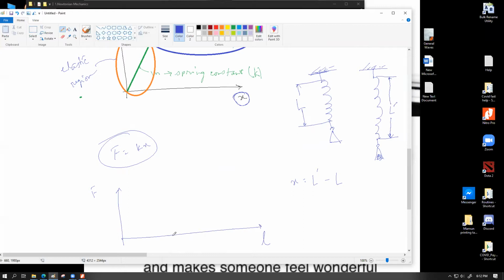So let's say the graph would start from this x-axis intercept, where this value is essentially capital L, the original length of the spring. Then as we start to apply load onto this hanger, if we apply bigger and bigger force, the graph is going to start from this point, and it's going to have the exact same characteristics as we have discussed earlier. So we're going to have a little bit of a straight line part. My hand drawing is not very straight, but bear with me. So this is the limit of proportionality.